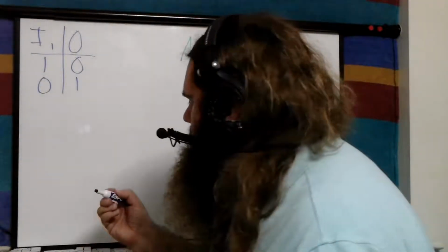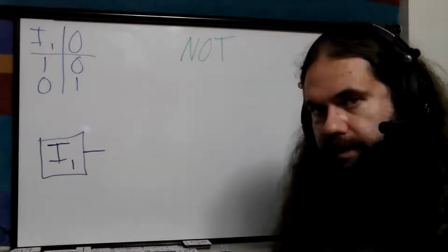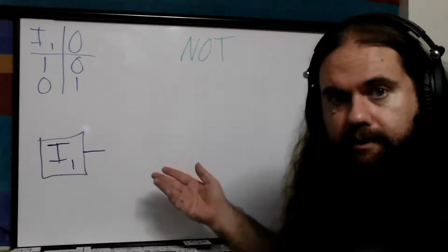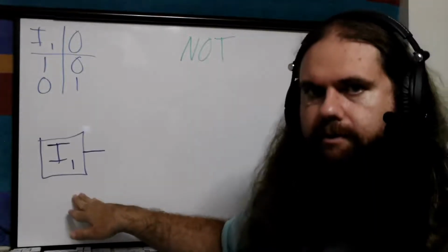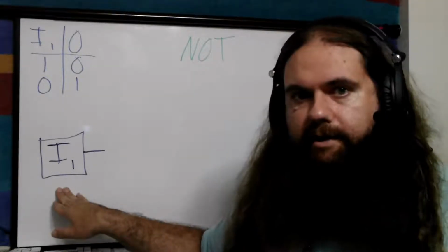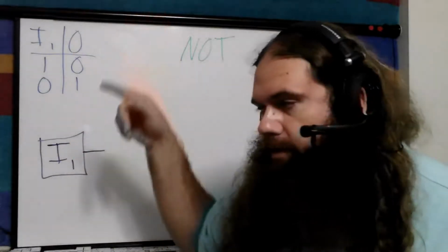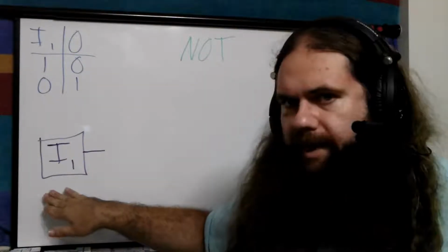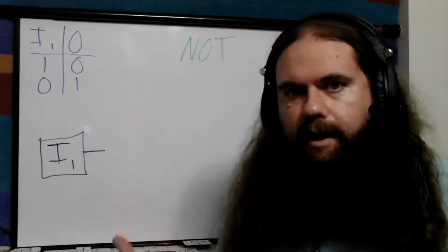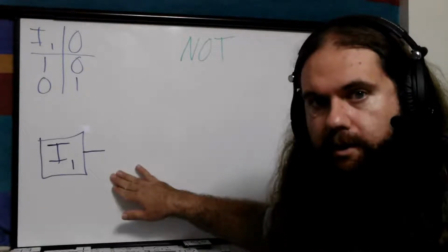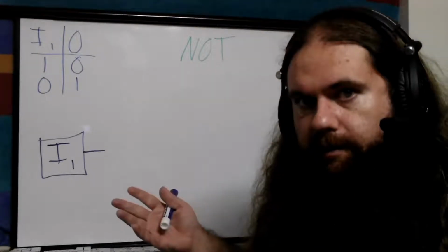Now let's say we have our input. We have I1 here. This is a voltage. It's referenced to the ground, the 0, the reference voltage. And let's assume that it's already current controlled. If this is a direct connection to power through a switch, you would have a resistor. If this is out of a transistor, you'd have a resistor through the transistor. Basically, we assume the input is well behaved. If it's not, add a resistor. All we're trying to say is there's no short circuit. Like I said, if there is, add a resistor, because we mostly care about the voltage here.